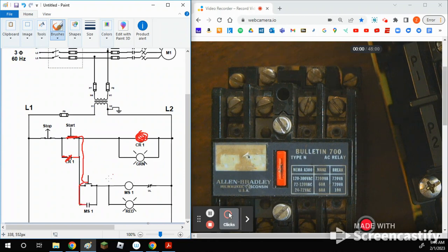Up to that point, none of this stuff is going to work. You see that? Once those wires are energized, you can then press this push button and turn the motor on, but you wouldn't be able to until then, right? Everything down here is everything you've done before. It's just our wire numbers are going to be a little bit different. We're adding this control relay in first.